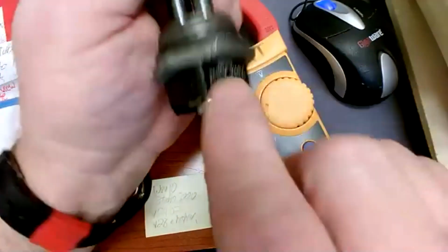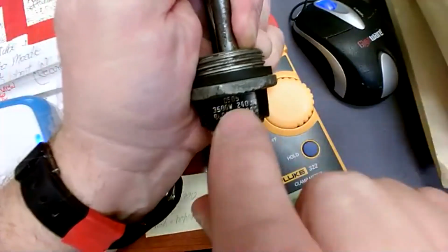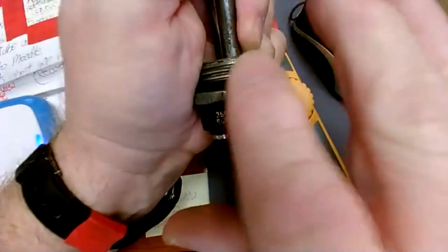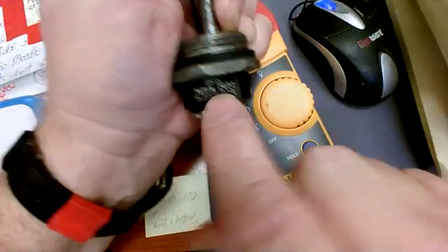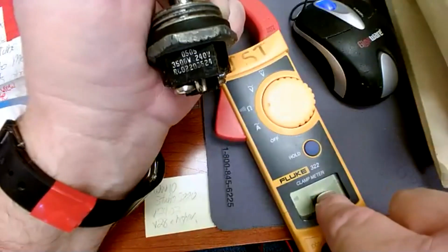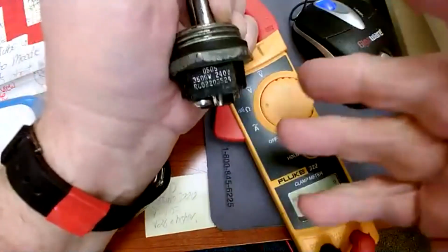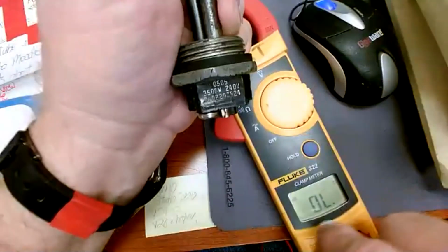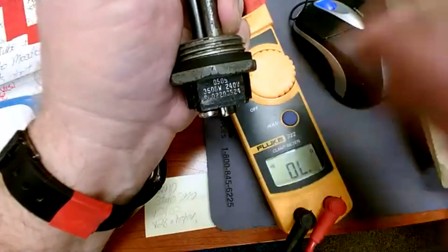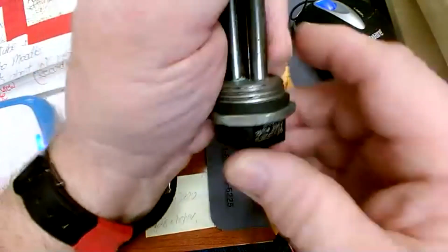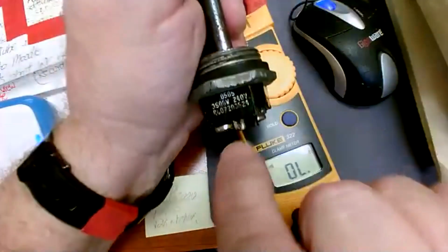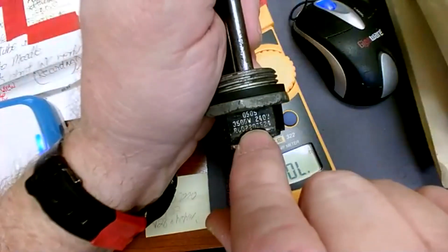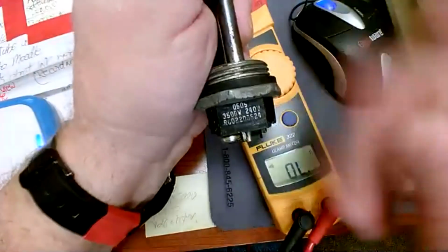So Ohm's law allows you to calculate the resistance of this and compare the calculation to the real number, the actual number, and see, does it match. And it's not going to match if it's burned open. It's going to be way off. It'll be an OL or be extremely high. And then you would know for sure, you just need to go to Lowe's and get one of these. And when you get one, of course, get an exact match on watts and volts. Get an exact match.